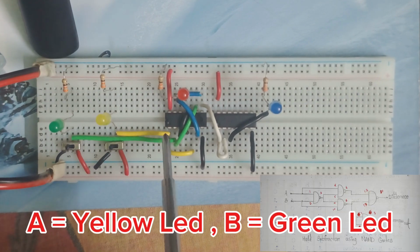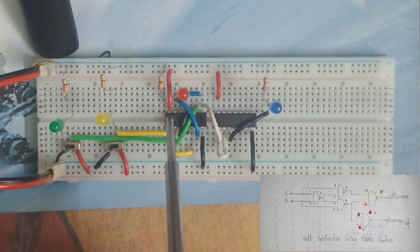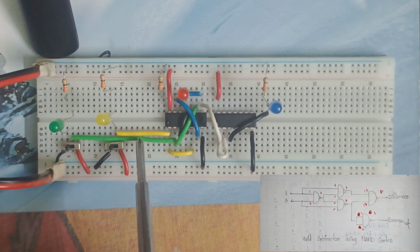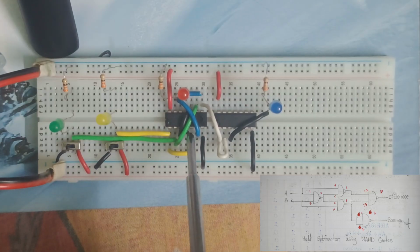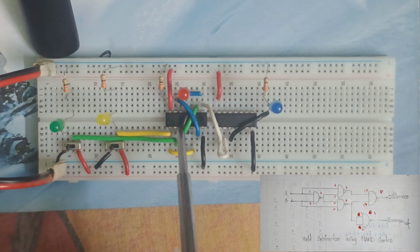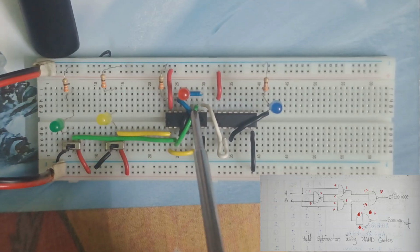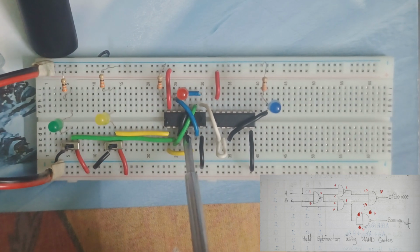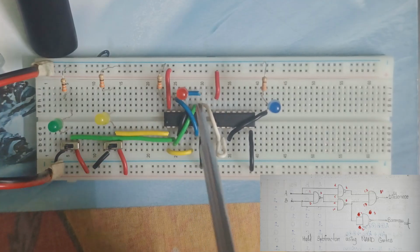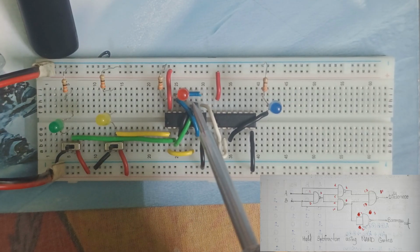So the first NAND gate of the first IC is operating on the basis of these two input signals and giving the output signal at pin number 3, and that pin number 3 is connected to pin number 4 via a very small black wire, and another small wire which is connected to pin number 3 and pin number 10. So this pin number 4 is the first input of the second NAND gate, and this pin number 10 is the first input of our third NAND gate.